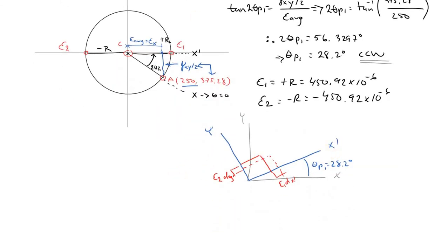We do have one more step, which is to draw out the shear strain transformation as well. Let's note where our maximum in-plane shear strain is. Similar to our shear stress, but recall our maximum in-plane shear strain is divided by 2.